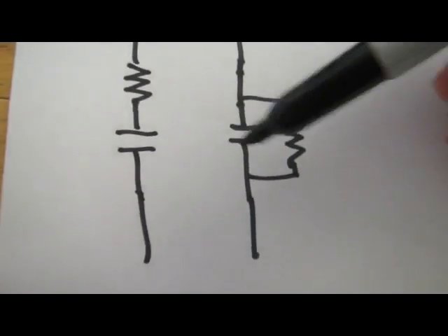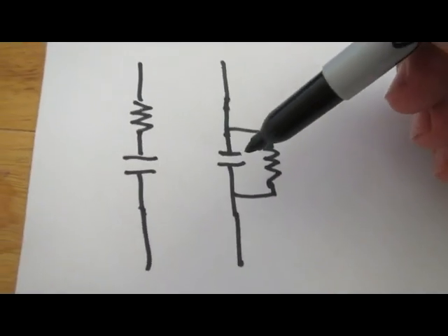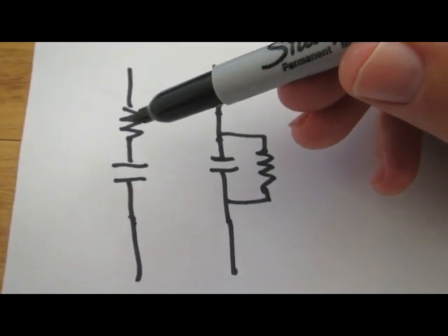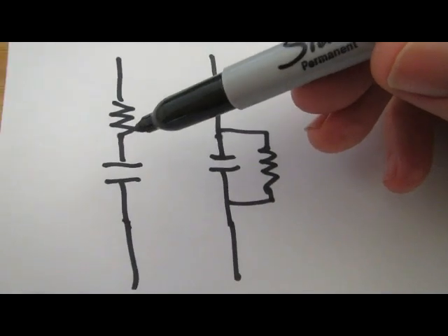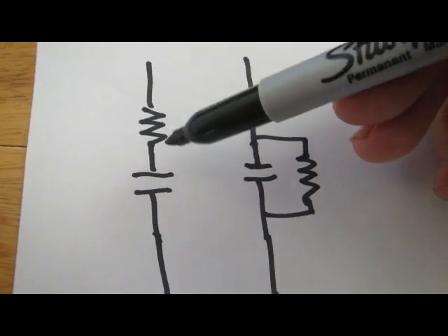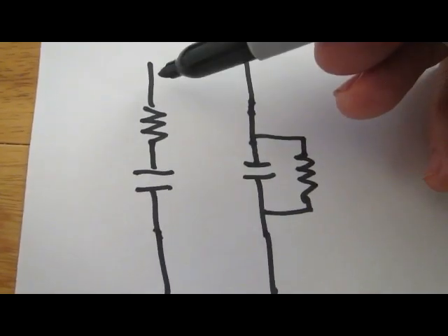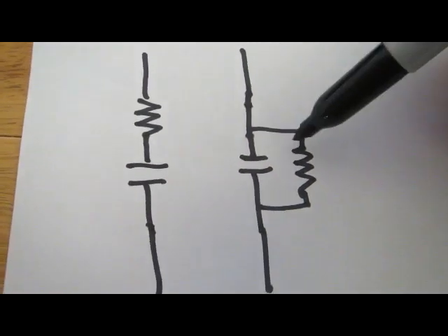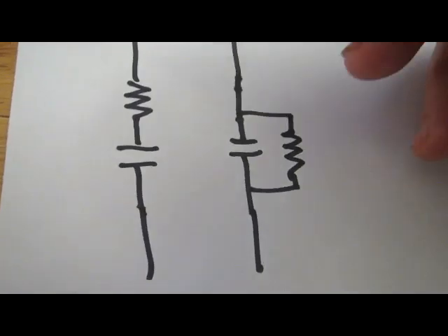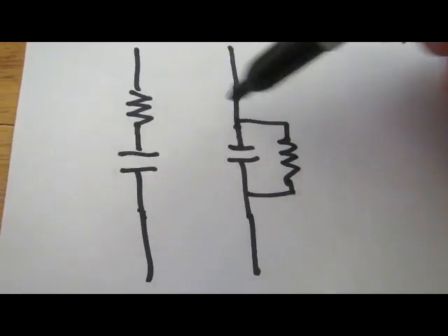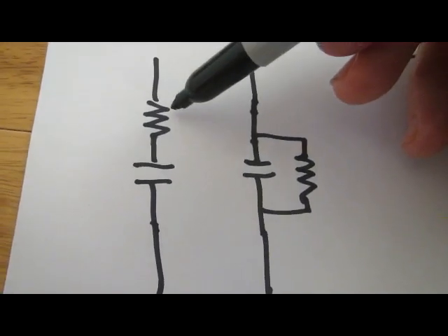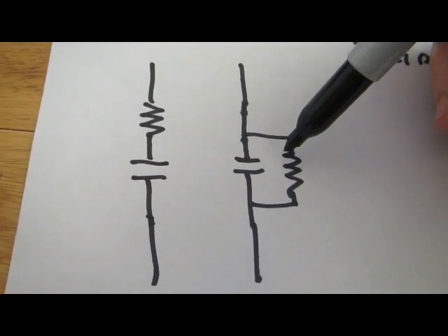Now this is the case where I've shown 2 capacitors here, but these are imperfect capacitors. This one has got some resistance in series with it, it's just built into the thing, so actually it's not a very perfect capacitor. It loses energy when we put energy into store and then take it out again, we don't quite get it all back. This one has got a resistance in parallel with it. Also it loses energy. Now these 2 circuits for alternating currents can be made exactly equivalent, and if each of these was in a black box we couldn't tell which was which.